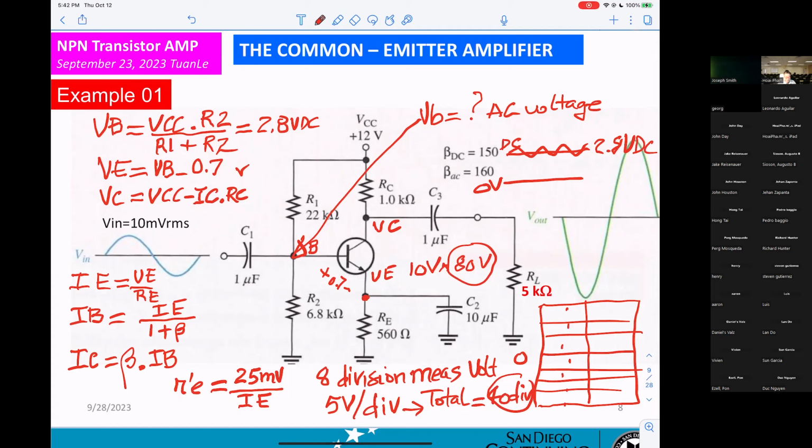When you're working on the oscilloscope, in this case you want to measure that small signal here. A very important thing you must memorize: set the scope to AC coupling. When you set AC coupling, this will be 0 here, and now you can see the sine wave sideways. They try to block the DC, 2.8 volts, no more. That's how you can measure.